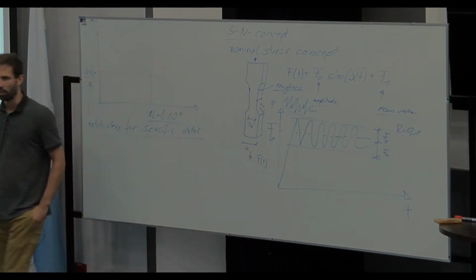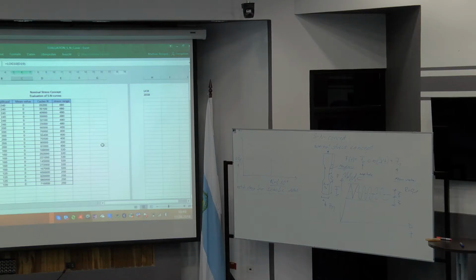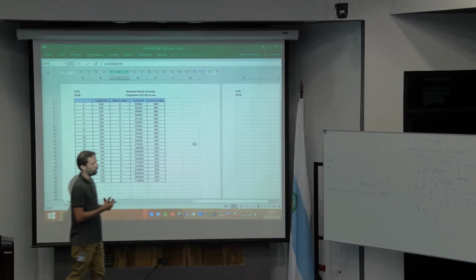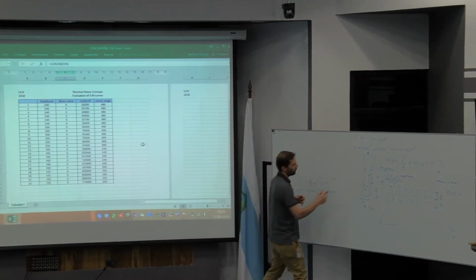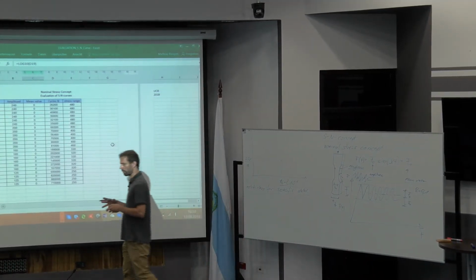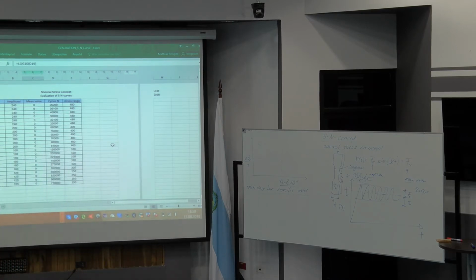And this is also something which you have to take care of if you produce a specimen, just to be sure that you have a quality of the roughness, that you have no inclinations or notches on your specimen as well. And so at the end your specimen shows you the same behavior and the same material properties, but also production properties, as your structure.